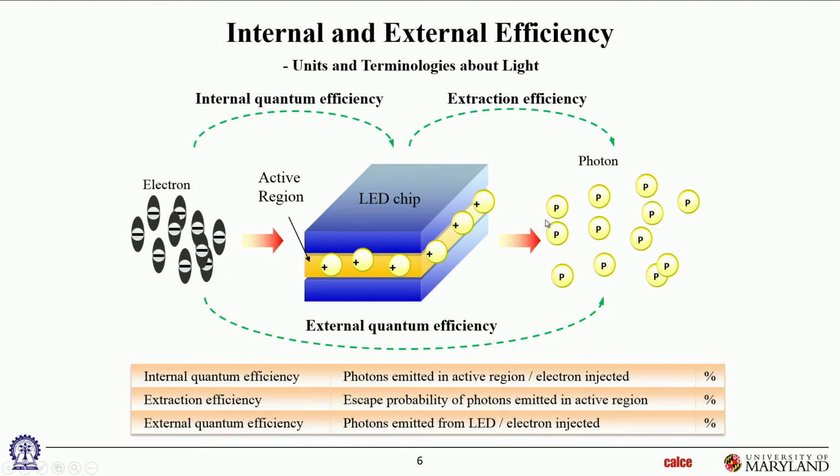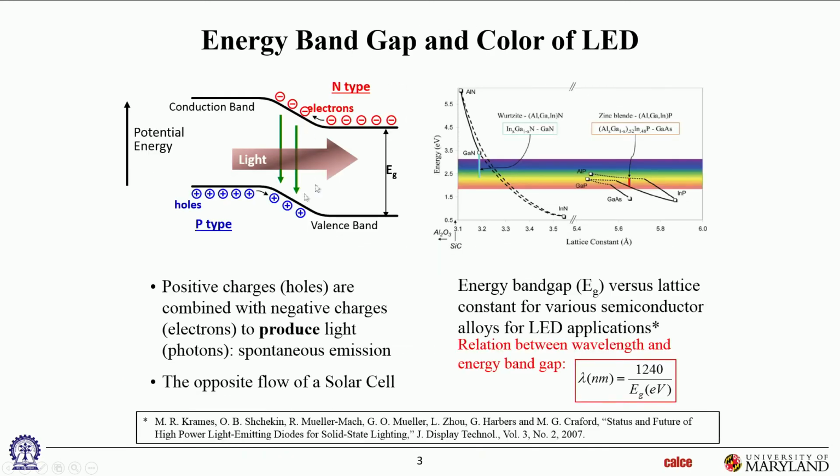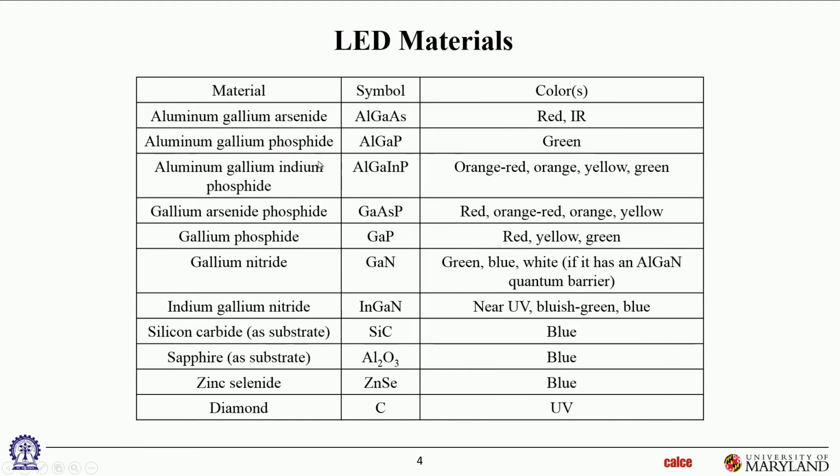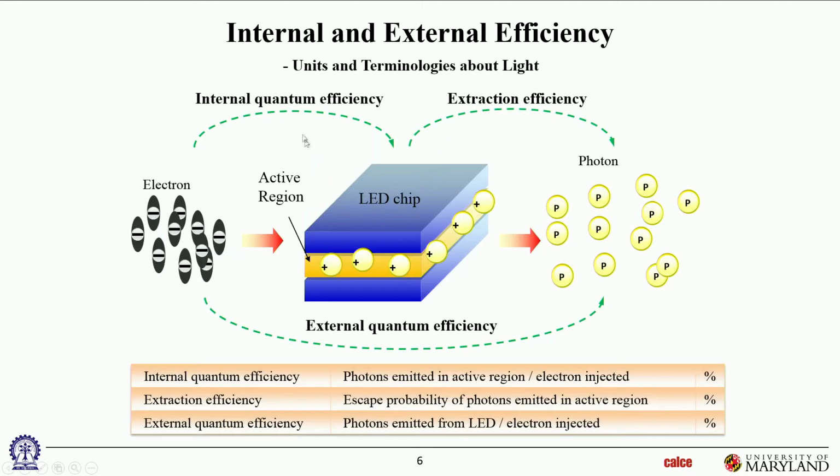And there are two aspects to that efficiency. That's what this slide is trying to show. One is the conversion from high energy electrons that you're putting in to high energy photons that are going to come out. That's your semiconductor level recombination. That's this stage. So there's an efficiency of that process: how many photons come out for the amount of electrons that you're putting in. That's the internal quantum efficiency. And then after the photons are generated, how effectively are you extracting them out as usable light? That's extraction efficiency. The packaging plays a big role in that also.